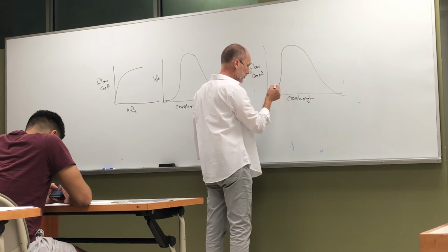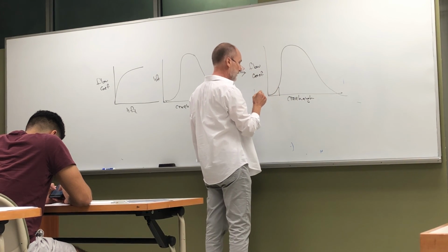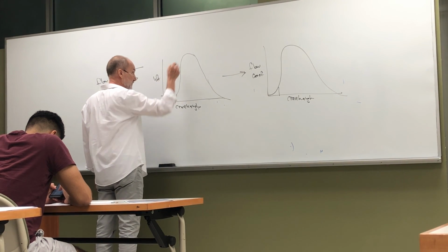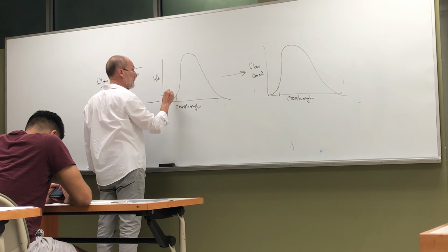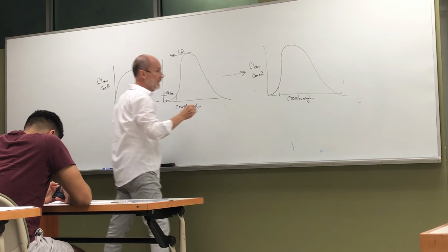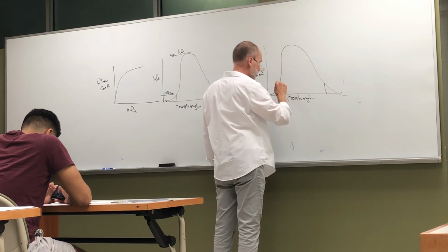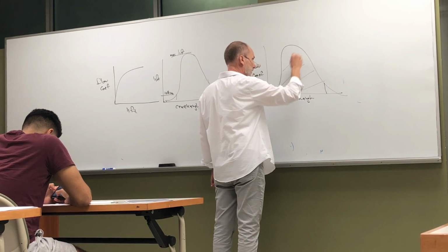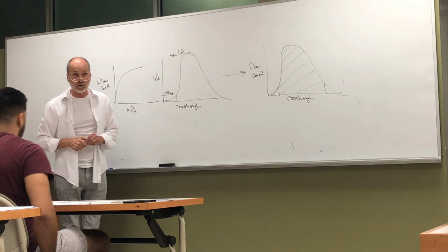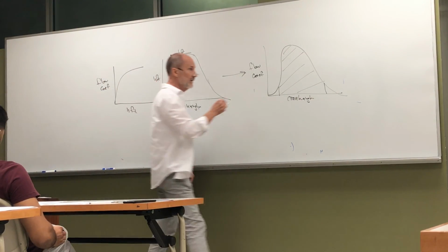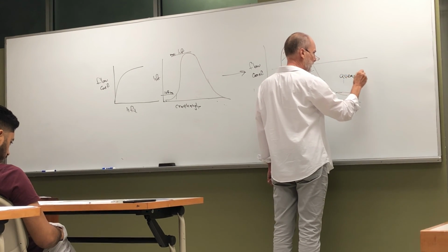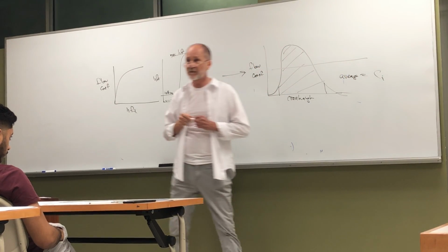And then I go to, in this case, a lift that corresponds to 10% of this maximum. Here's the maximum lift. And I locate those two points, and I take this entire area, I take the average of that, and that's the flow coefficient that goes into the Mach index number. This average here equals our flow coefficient for the Mach index number.